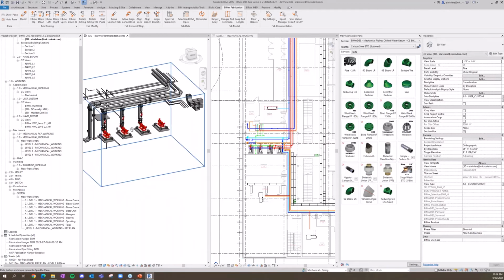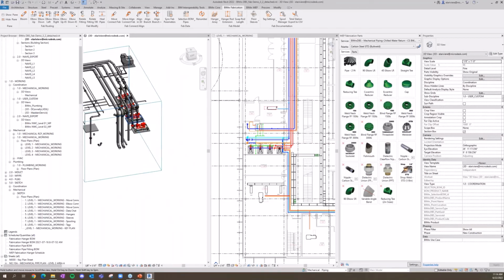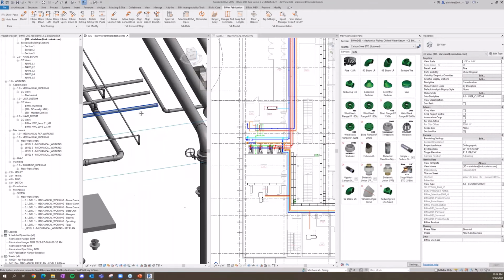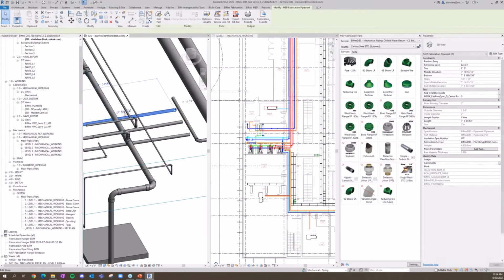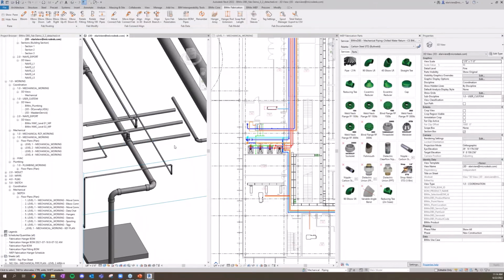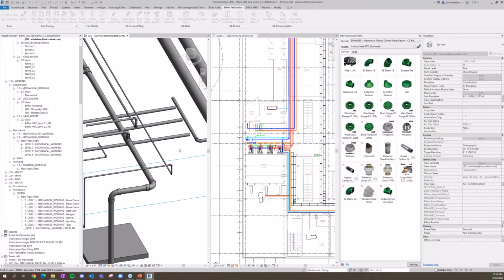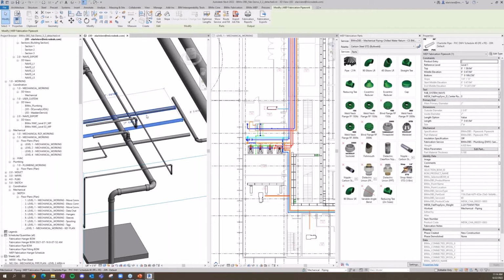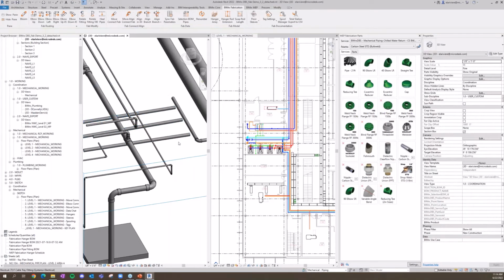So that align branch is extra cool because it works with more than just flat pipe. If we take a look over here, I've got a 1/8 inch slope, I've got a 1/4 inch slope, and I've got no slope. I can use align branch on the 1/8 or the 1/4 to align both of those slope pipes up, maintaining their individual slopes, but allowing me to use trim extend for that final connection. Again, no transitions, no nothing, perfectly flat.